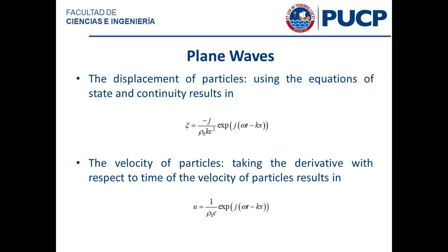Okay, the P is the Helmholtz pressure, right? Yes, correct. So P is equal to e to the j omega t minus kx. We divide by that expression of U over there, and what we end up with is P divided by U equal to rho naught c. So that means that for a plane wave, the specific acoustic impedance is equal to the characteristic acoustic impedance.